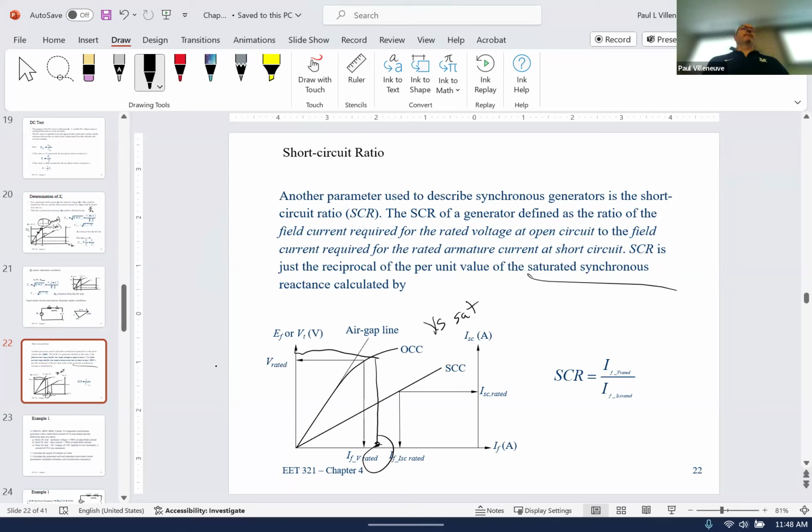Okay. Yes, sir. So for a typical generator, the EA is going to be positive. The angle delta is always positive if it's a generator, negative if it's a motor. Would the IA angle also still be positive for leading? That determines, it depends on whether it's leading or lagging. If it's leading, positive then?